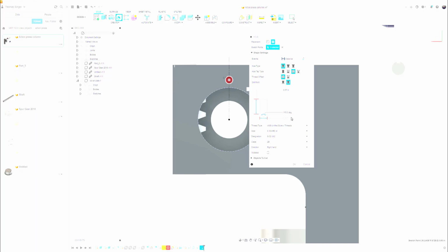But the default is the diameter that is given, but it doesn't know the depth. So realistically, you can control the depth on this particular object. Now the width of the column is only 1 inch, so if you went 0.457, you're going halfway into that column. Well, halfway into the column may run into the rack. So let's do it as a 1/4 inch, to hold the cover plate on, 0.25. So the depth is going to be a 0.25 depth, and we'll choose OK.